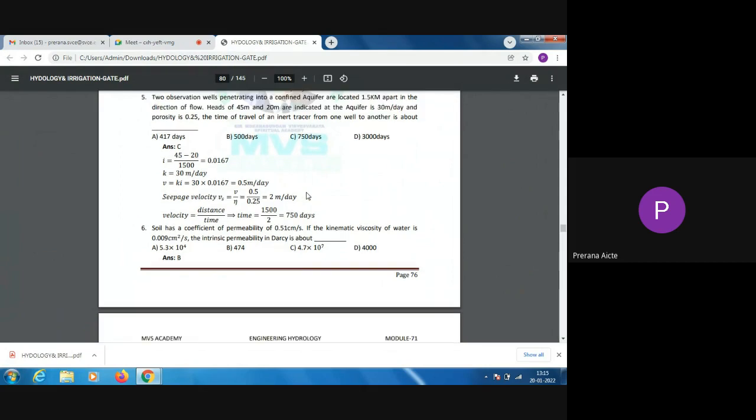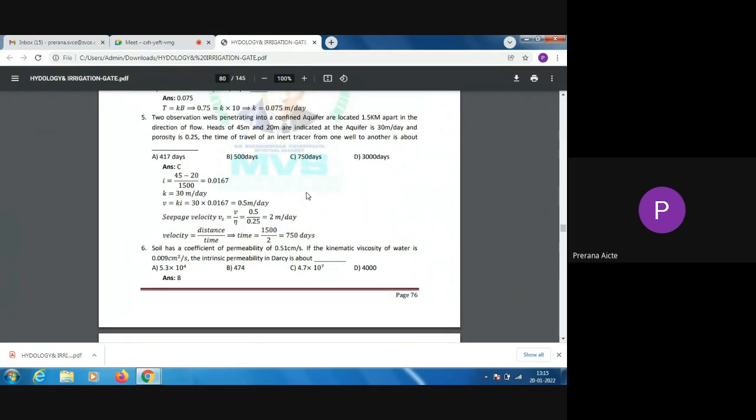Okay, then, see, you could do this. Two observation wells penetrating into a confined aquifer are located 1.5 kilometer apart in the direction of flow. Heads of 45 meters and 20 meters are indicated. The coefficient of permeability of the aquifer is 30 meters per day, and porosity is 0.05. The time of travel of a net pressure from one well to another is about...